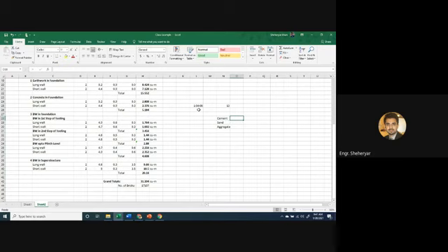So the quantity of cement which will be required for this 5.184 cubic feet of concrete work will be 1. Let's write the ratio here, 1:4:8, right? Yes sir. Okay, the quantity of cement will be 1 divided by 13. Out of 13, 1 part is cement, multiply it with the volume of concrete which is